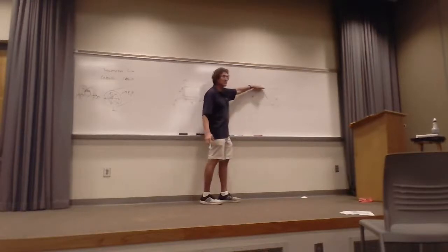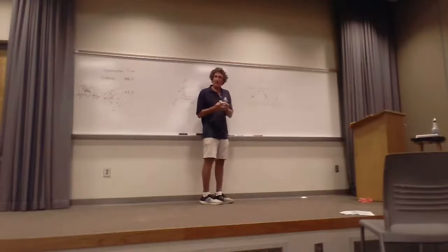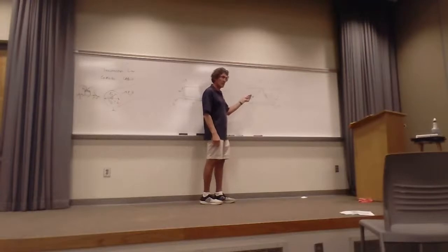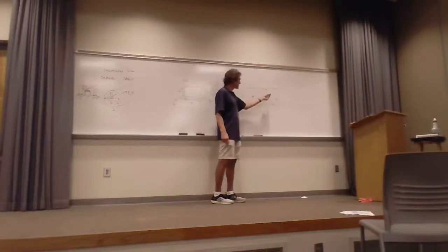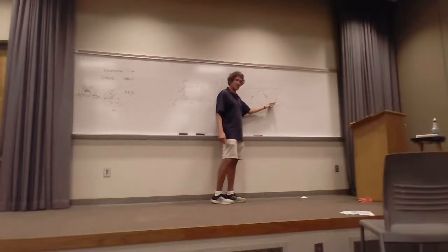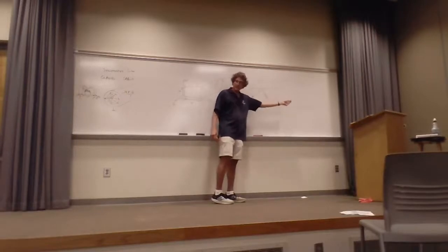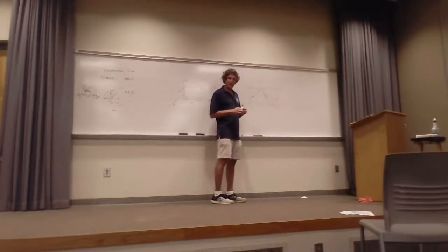The tangent electric field here has to be zero. Do y'all follow me? If that's a good conductor, we know E tan is zero on a good conductor, right? It shorts it out. So if the electric field's in this direction coming out of the board, then when it hits here, it would go to 0. All right, this would be the electric field coming out of the board. It would have some relative max, but when it hits here, it would go to 0 again. And the same way, you all follow me on that.